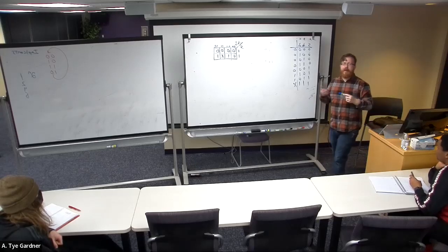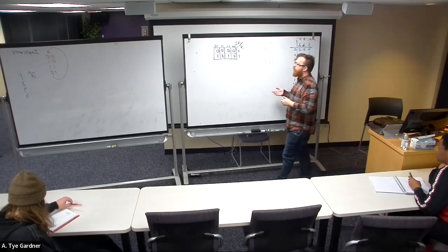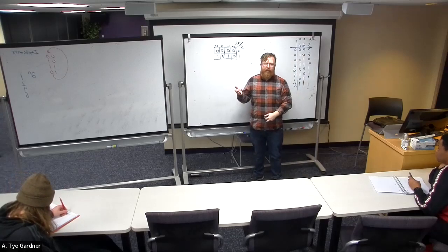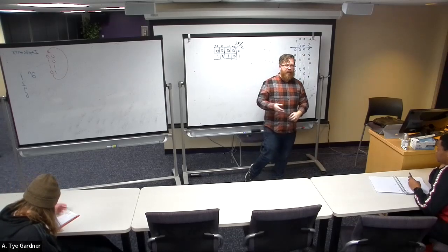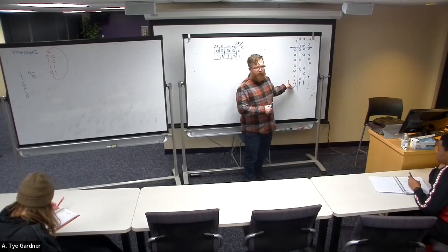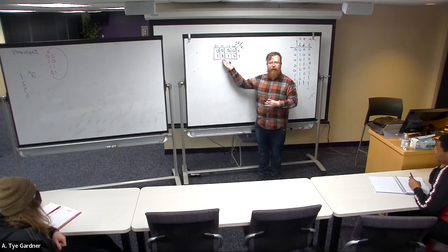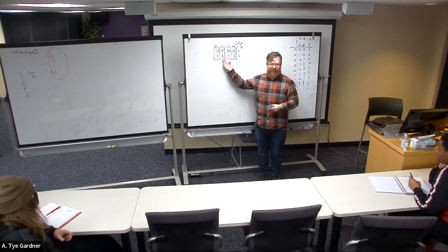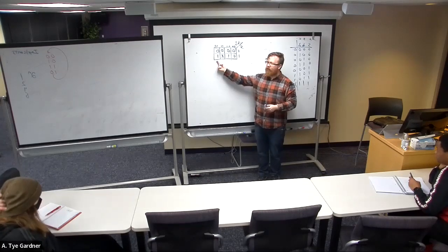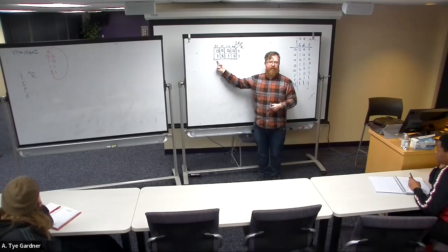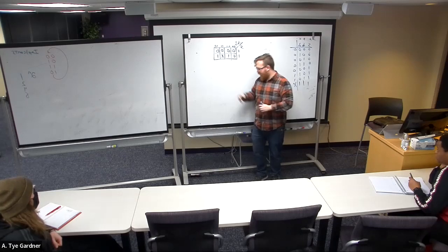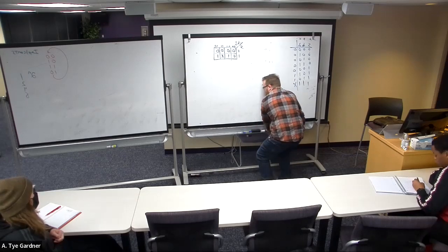Now, remember how when you started simplifying this during the lab, it helped to add an extra term, and it turned out that it was easier if we chose this one to be a 1 than if we didn't? This is why. This K-map visualizes why it was easier to choose 1. Because instead of having 2 circles that are on their own, meaning each implicant has 3 variables, with the don't care, I get to do